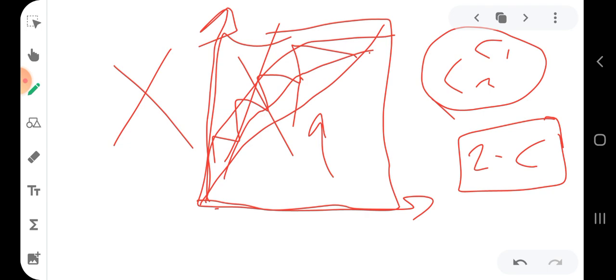Okay, so again, you cannot use graphical methods to get a solution for multi-component distillation, but you can use them only for the two components. But when it comes to the equations that you are using to predict the number of stages for the multi-component, you can use them also if you have only two components. Nothing prevents you. Okay, it is all about the accuracy. So at the end of the day, both the graphical solution and the equations that I'm going to present today are just numerical approximate solutions. They are not exact analytical solutions.